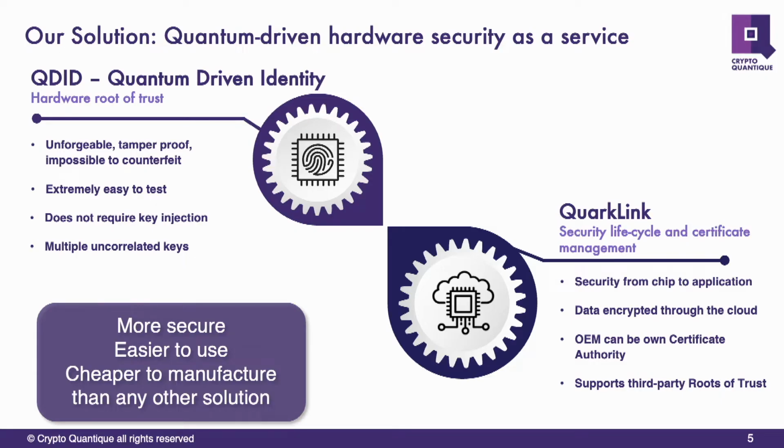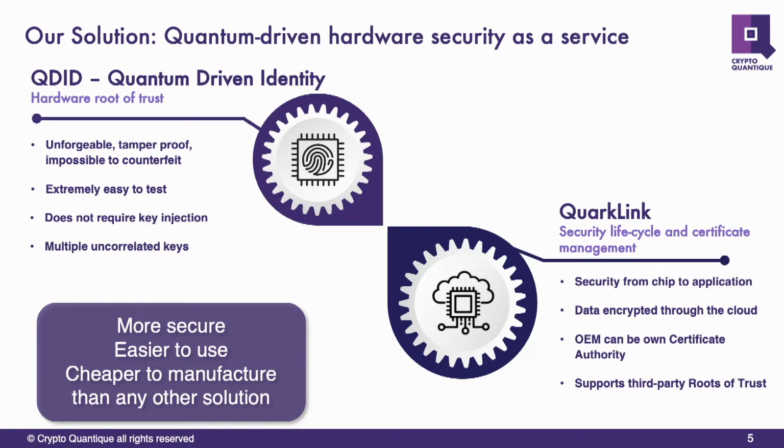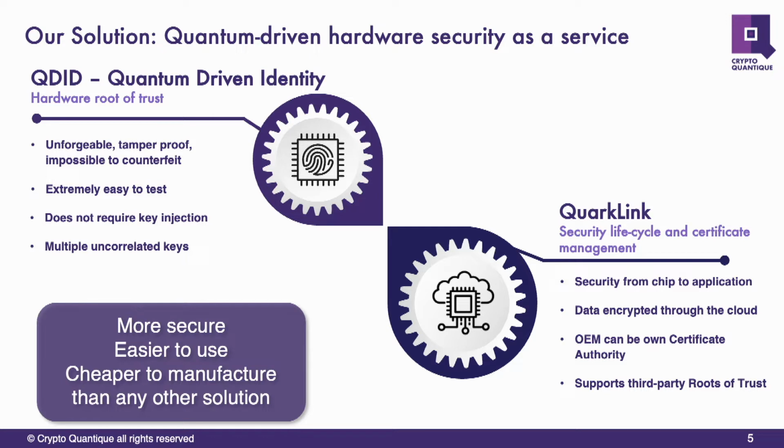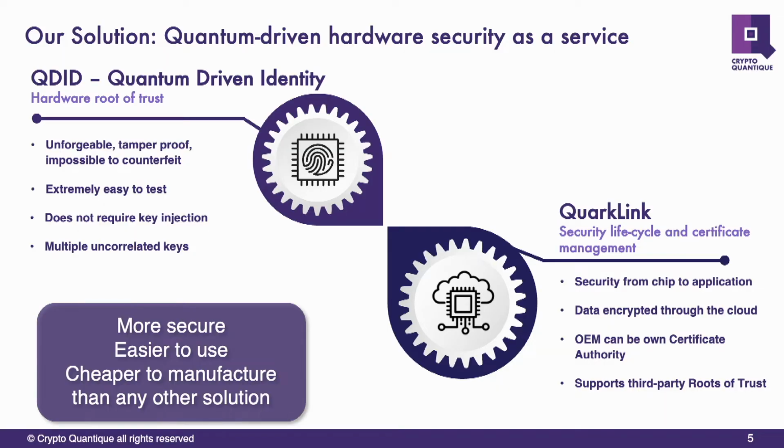It's based on a quantum effect. We measure quantum tunneling currents in a transistor. That gives us very high entropy and our unforgeable capabilities. It creates a unique identity in every single chip the device is integrated in. Every one is different, and it comes from very high entropy. So what does this mean? It means we can simply manage the identity of the device throughout its life cycle. The security is based on that provable identity, which is based on this PUF device, and it means we can do zero-touch capability throughout the life cycle of the device. Over there, you've got a diagram showing the actual currents from a PUF that we measure. We measure down to tens of picoamps of the quantum tunneling currents of the transistors in the array. I'll talk about that a little more as we move on.